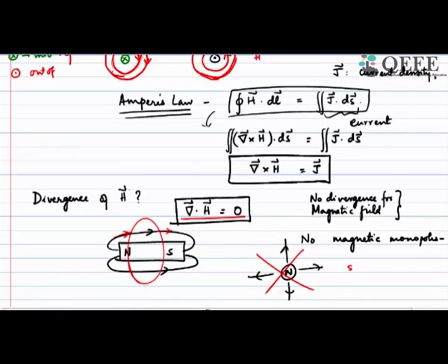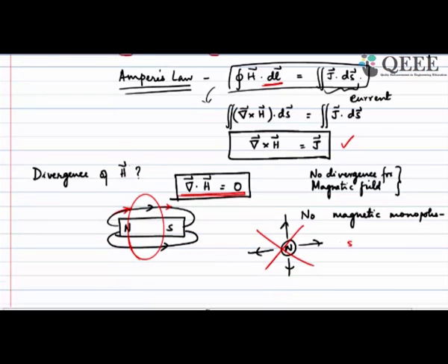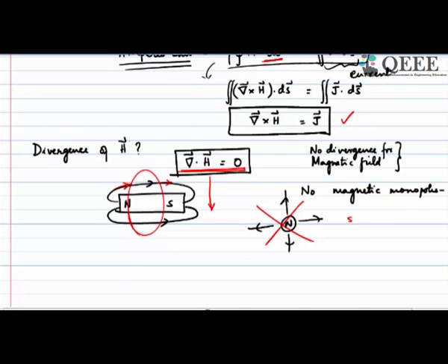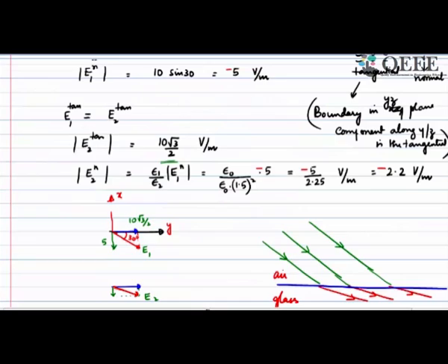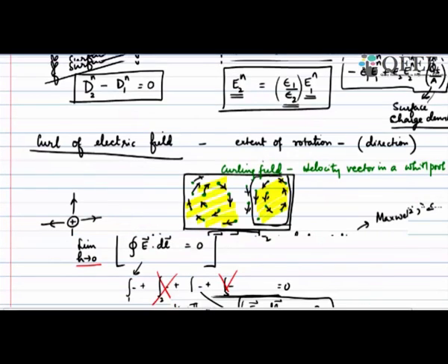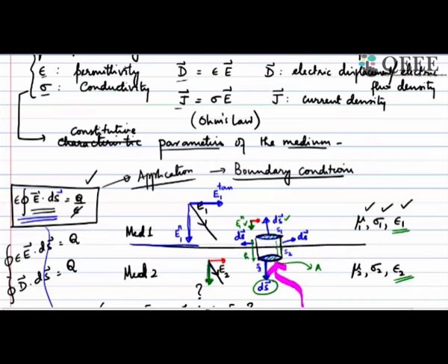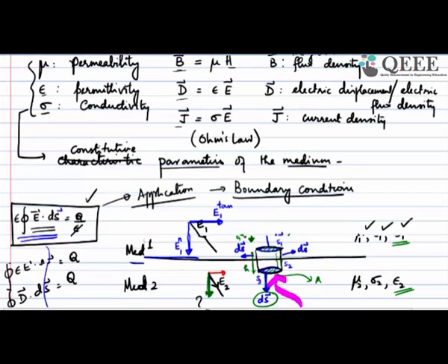You can work out similar boundary conditions for magnetic field. This will give you a boundary condition for the tangential component, because the line integral gave you something for the tangential component, and you will get something for the normal component from this. You have the corresponding integral equation, which is the surface integral of H dot dS, just like how you had D dot dS. Similar to how you wrote for the electric field, you wrote that D dot dS is q, the right side is 0, so here H dot dS is going to be 0.